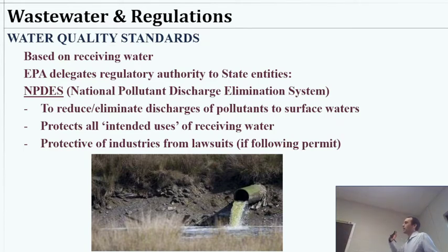But anyway, if you think about a standard septic system, your biggest potential problem is clogging the pipes that leach out into a field, because the septic system will have an anaerobic bioreactor, then it acts as a sedimentation tank too, and it slowly discharges into a field, and it kind of waters your grass, and that seeps into the groundwater, and ideally you don't get human exposure to that, and that filtration through the soil prevents too much travel of pathogens.